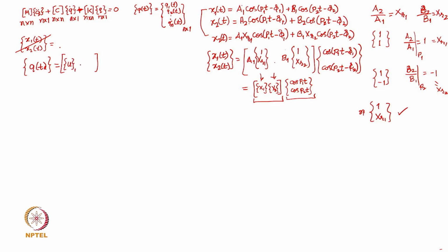If I consider this to be n degree of freedom, then u1, u2 up to un would be these mode shapes or vectors containing the relative displacement amplitudes of each degree of freedom, and then multiplied by what I will use here, a coordinate which I call a principal coordinate or a normal coordinate, okay, eta(t), which are nothing but these harmonic time functions.